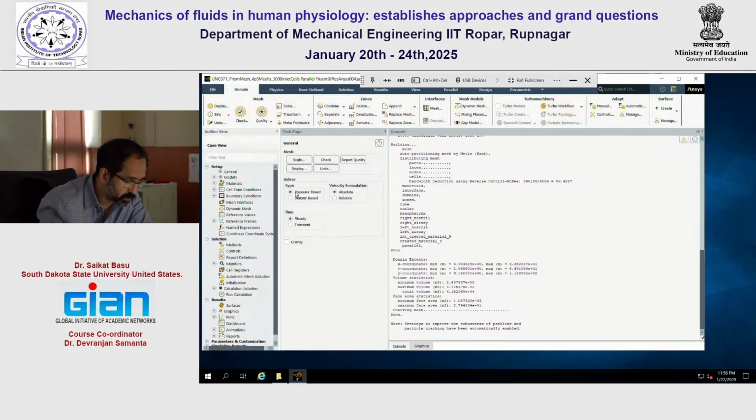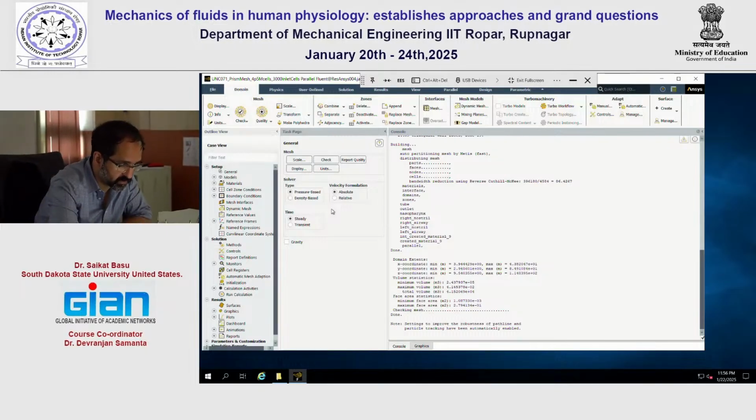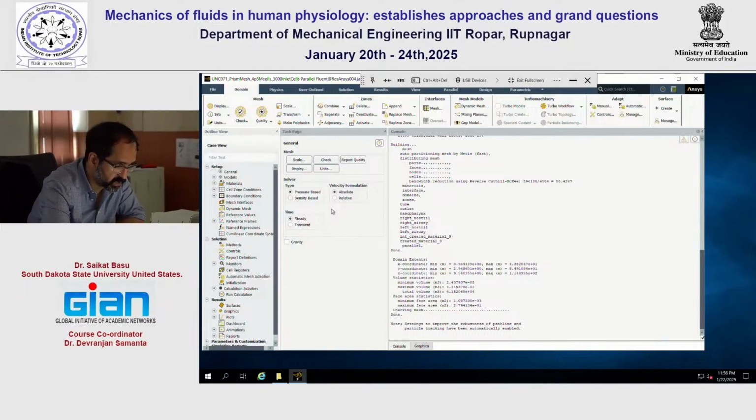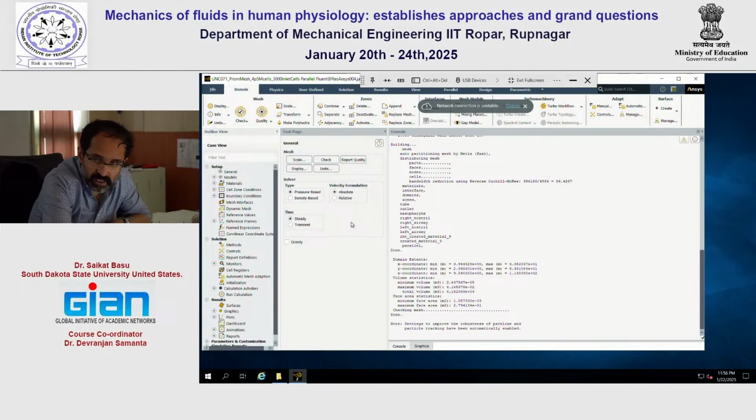And then this is going to be a pressure based solver. So the flow is driven by the pressure gradient. Should it be steady or unsteady? Based on our understanding of the mathematics from the first few days, unsteady, right? That is key towards what we did yesterday, that in the upper respiratory tract, the time varying component is strong, and that should dictate what you choose over here.